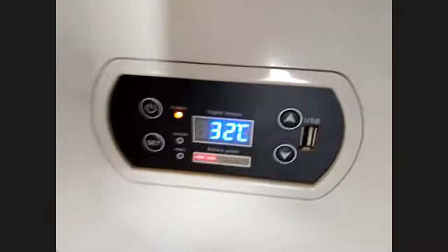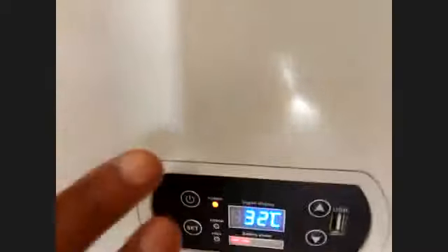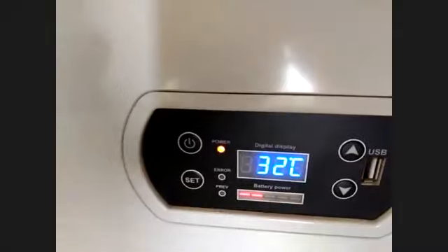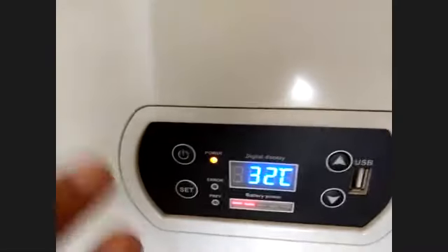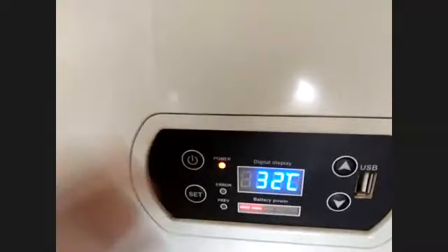One battery is required, and a 100 watt, 18 volt panel is sufficient. The battery is 200 ampere hour and 12 volt, and the controller capacity is 20 ampere and 12 volt. And it is 100 liter.